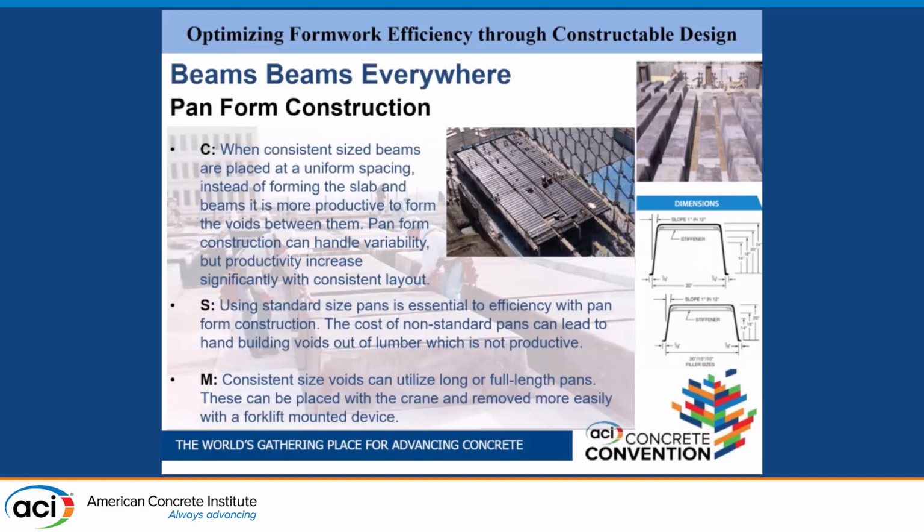So, some things on beams. Pan form construction has been around for a whole long time, and I think it should see some resurgence. Pans are a great way to have a stiff floor system but reduce the amount of concrete that needs to go into it. The overall depth can be pretty high, but the effective depth, the amount of concrete you're putting in, is pretty low. So from a carbon reduction standpoint, pan systems are really good.